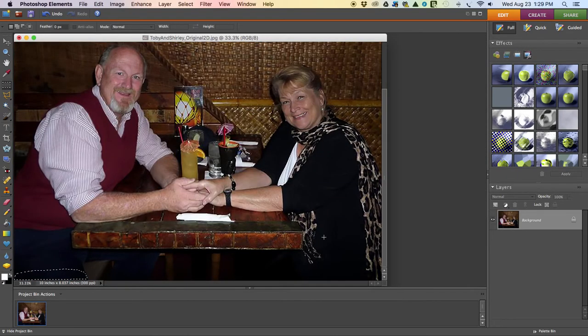So you study it, you go back to your selection tool, your polygonal lasso tool. Now here you have to make sure before you begin cutting into the second depth slice that you have this here selected. It's called Add to Selection. You notice when you have the selection tools activated, you have these options up here, and the default here is called New Selection.